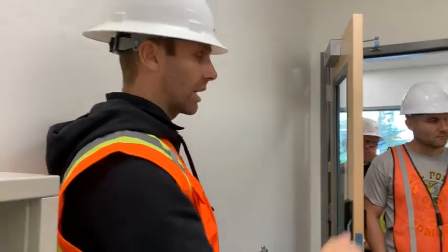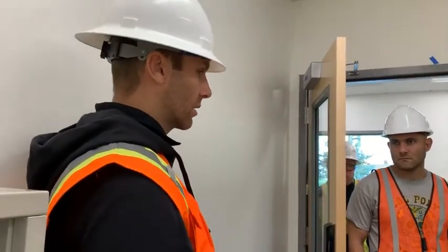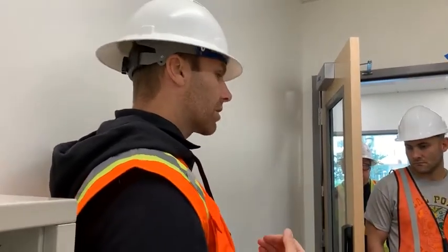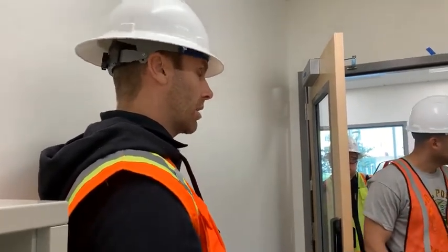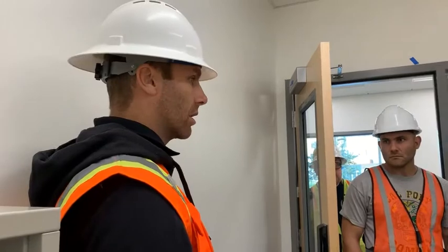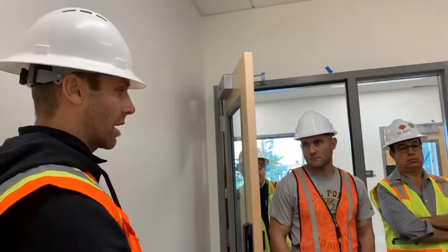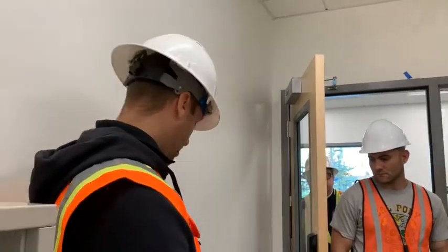okay? And once again, if I want to turn off the switch, that's fine. I have to manually turn it back to come on. And even if it's off, if the room is occupied, that receptacle is still hot. All of those should be marked. That's a code thing. We can see they're marked.